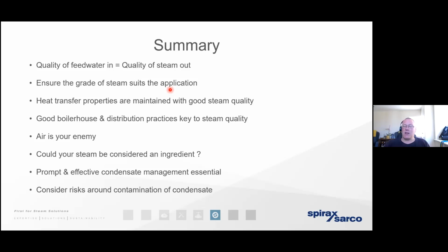It depends whether we're plant engineers or process engineers, whether we're using the steam for direct injection or in a closed loop system. On the plant side, it means a poor condition of steam. It can result in erosion, corrosion, water hammer, poor heat transfer. On the process side, a poor steam condition can result in contamination to the process. Everything starts in the boiler house.